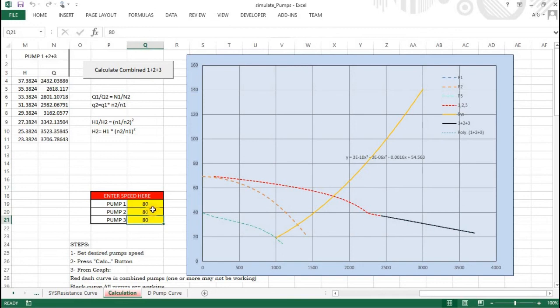So I have to monitor those 3. From a control point of view, how will you know where you are operating? There are a couple of things. If you have a flow meter in front of each pump, I don't have. Those are motor operated pumps, so I can measure the current. The current is related to the load on the pump, so I would know whether those pumps are loaded or not loaded. You can figure out with the current instrument if each pump is loaded.